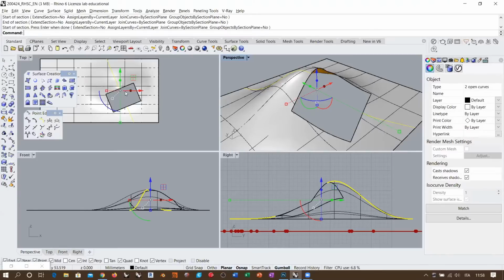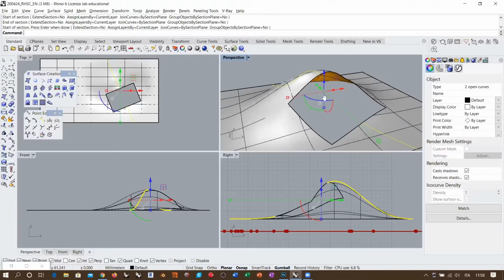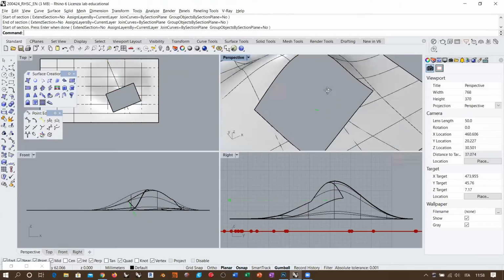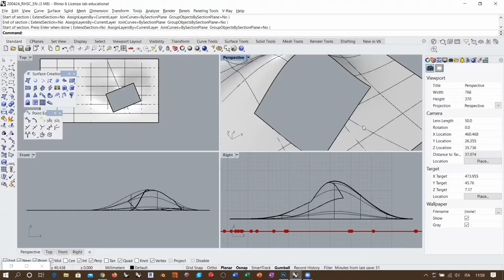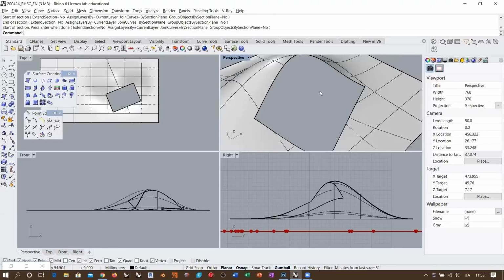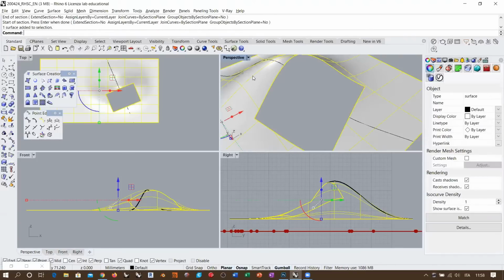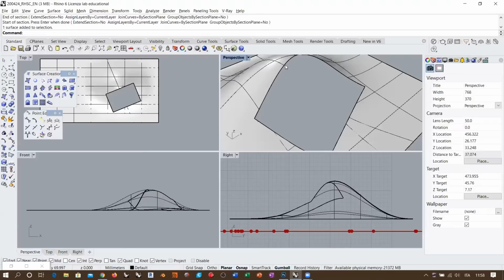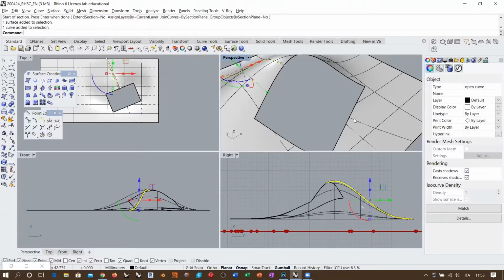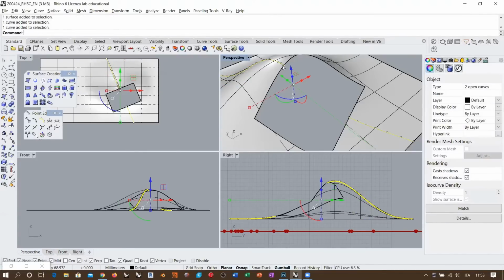There is no problem, but I just need to simplify the process. So we have these two lines belonging to the surface. If I want the inner surface to be curvature continuous with the outer surface, I can also create an interior edge here, which is curvature continuous with this line and this line. This would serve as an internal guide for my surface.